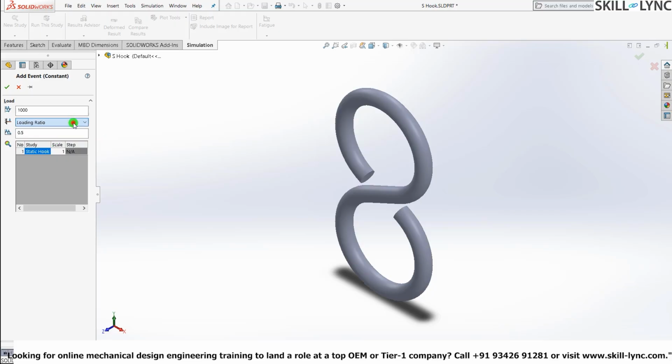And the last one is find cycle peaks. Find cycle peaks is based on multiple reference studies. The program uses the stress results of the specified studies to find cycle peaks that give the highest alternating stress for each mesh node. An example of this would be if you are evaluating a scenario where a dead load is present. So in short, what this does is it will run multiple studies to identify the highest peak of the alternating stress among the studies that are mentioned by the user.